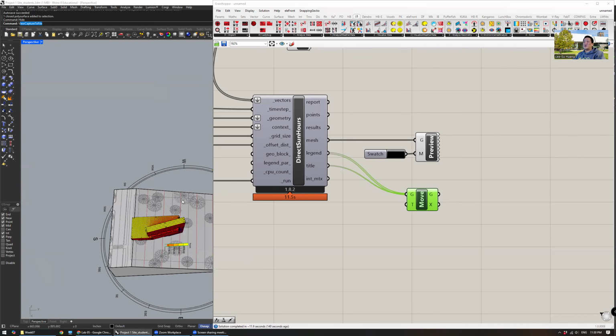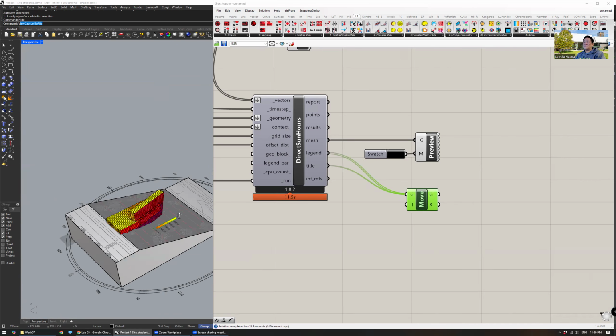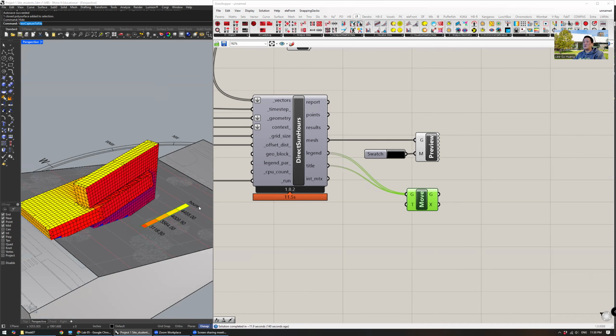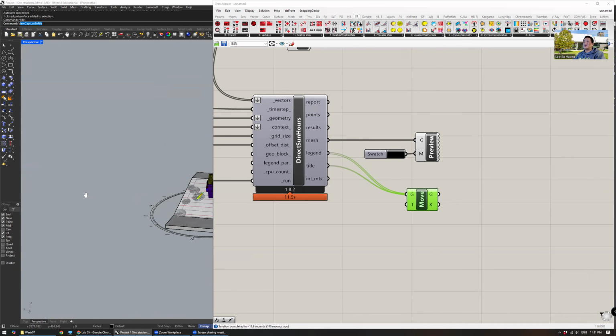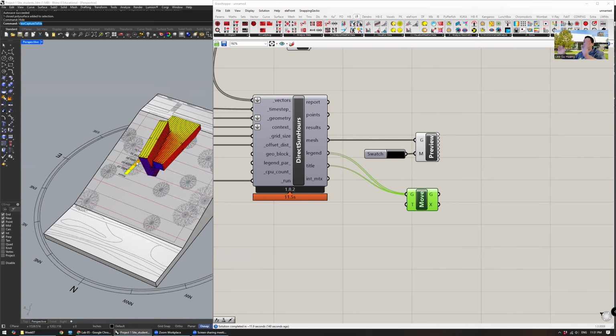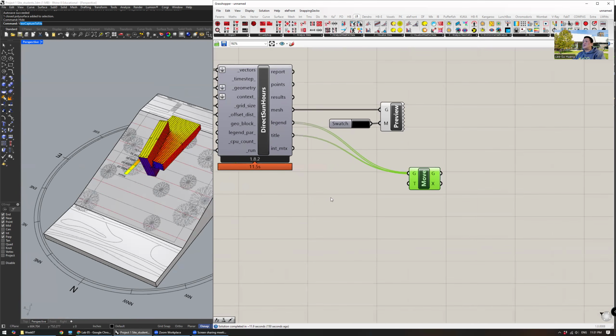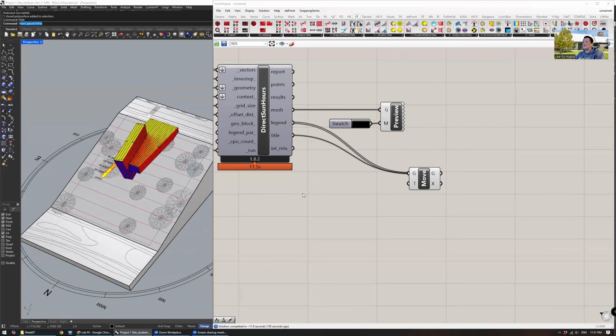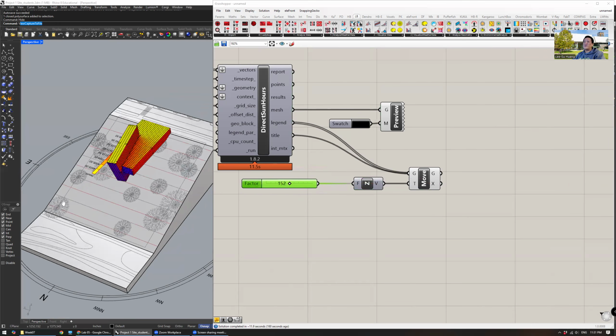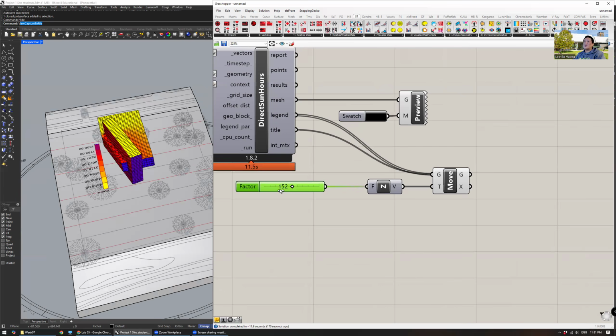This obviously will eventually depend on where you want to frame this view. Is it this corner? Then you'll see it there. If it's this corner, it might be inverted, so you have to flip it around, all this sort of stuff. But first we want to move it out of the ground. So we'll use a unit Z vector. Search unit Z and do a slider 0 smaller than 300, let's say. That should give us enough clearance. So I'm bringing it out of the ground.